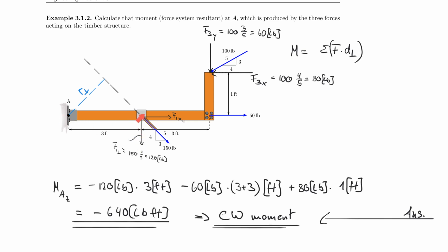In this case, you have a force that isn't going negatively down, but it actually rotates clockwise, and therefore it's negative. That is the reason why you see this negative. Not because the force is pointing downwards, but because the force is rotating clockwise. This can be deceiving, right? If this force was going downwards on this side, then it would actually rotate counterclockwise, and therefore it would be positive. So it really always has something to do with the reference point and the point of interest. Please don't confuse direction with rotation.